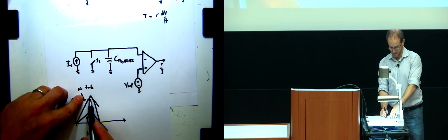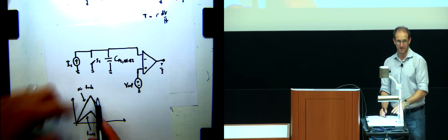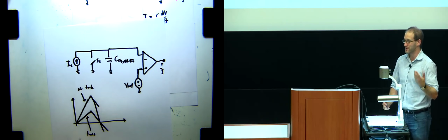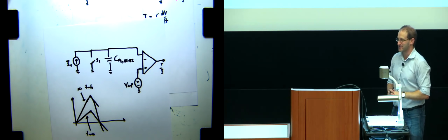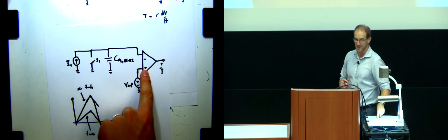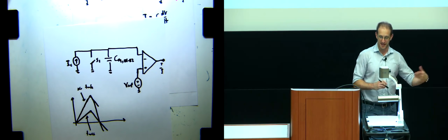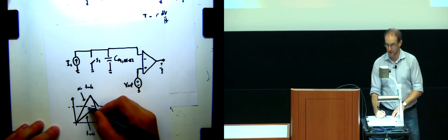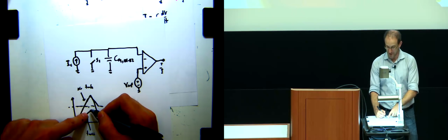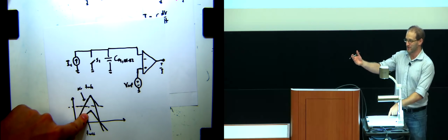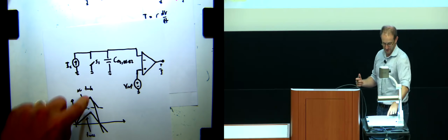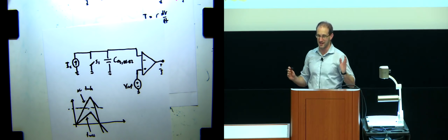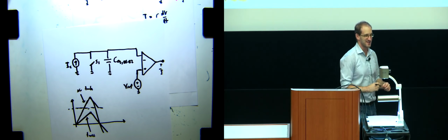So basically, when you didn't have a touch, the amplitude of that waveform was larger, like the peak point you would reach would be larger than in the case where you had a touch. Here I'm setting things up this way because I'm going to be detecting whether this amplitude is above or below this line here. If it's below it, I want the sensor to have a positive voltage saying yes, there was a touch. If it's above it, I want the sensor to have a negative voltage saying no, there was not a touch. That's why I set the comparator terminals the way that I did.